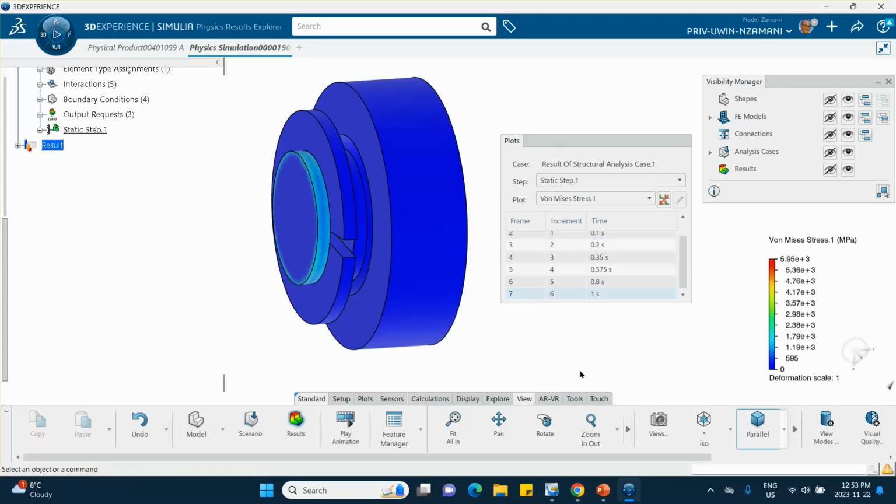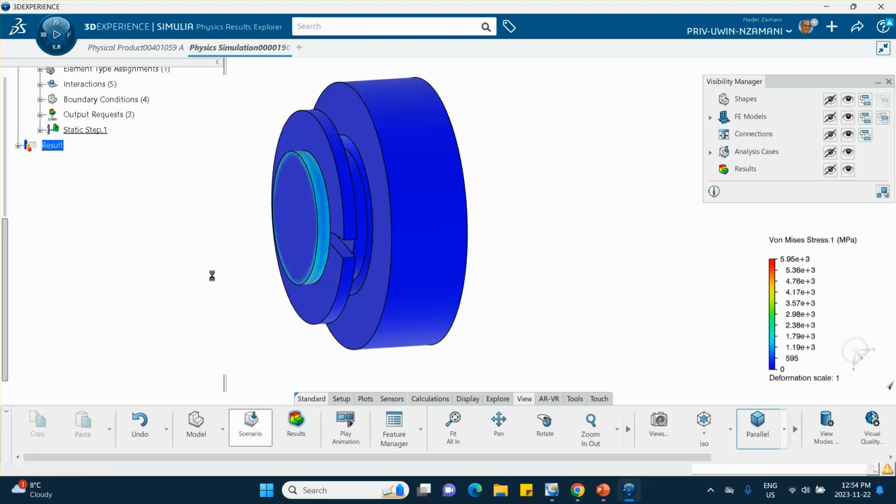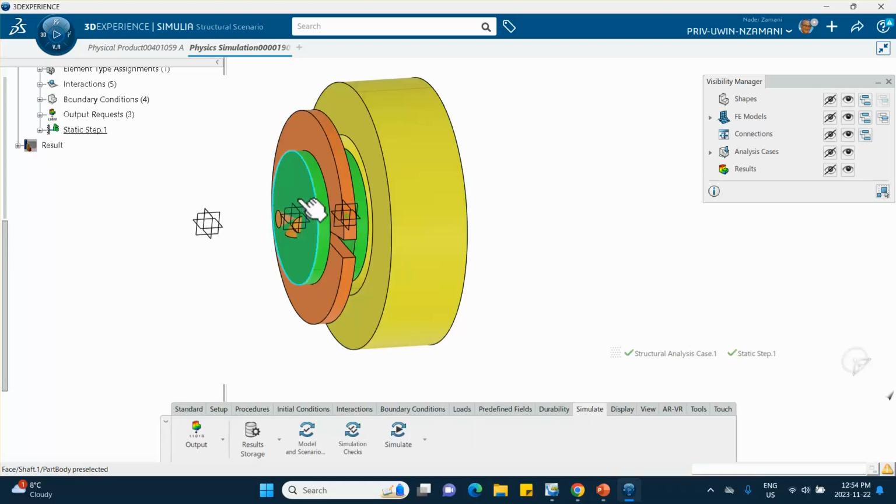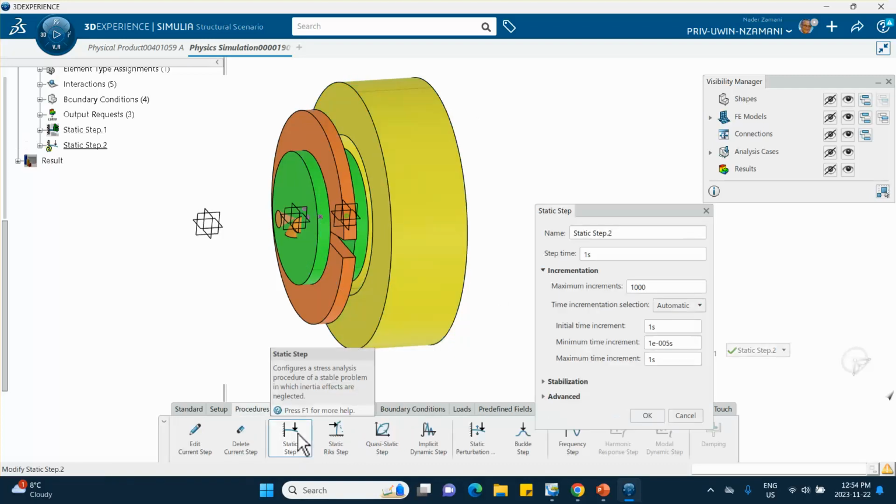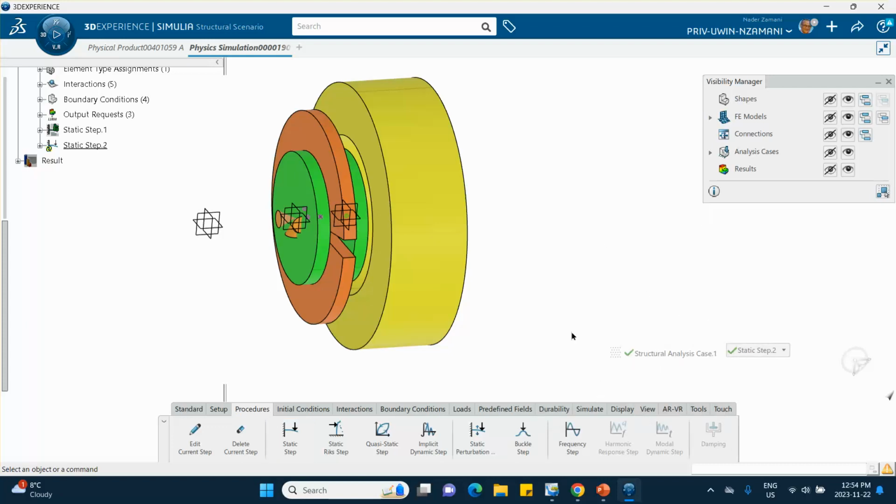Okay, good. And then we're going to go back to scenario and we're going to push this thing to the right by 20 millimeters, so that this C-clamp barely establishes contact with that face of the yellow piece. So we're going to go to procedure, another one, and I'm going to call this thing point one. Once again, give it point one initial. You say okay.